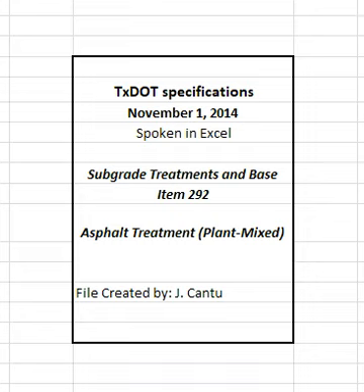2.2.1 RAP. RAP is salvaged, milled, pulverized, broken, or crushed asphalt pavement. Crush or break RAP so that 100% of the particles pass the 2 inch sieve. Use of contractor-owned RAP including HMA plant waste is permitted unless otherwise shown on the plans. Department-owned RAP stockpiles are available for the contractor's use when the stockpile locations are shown on the plans.